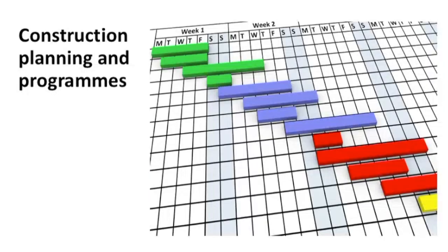Construction project planning is a method of determining what is going to be done, who will be doing it, how long it is likely to take, and when they will actually be carrying out the task. Construction project plans describe sequences of activities, including dates, and they generate all of the tasks in the critical path, i.e., the things that have to be done in sequence and therefore determine the length of the project. They also determine the order in which tasks have to be conducted and any spare time or float which has been included in the project consideration.